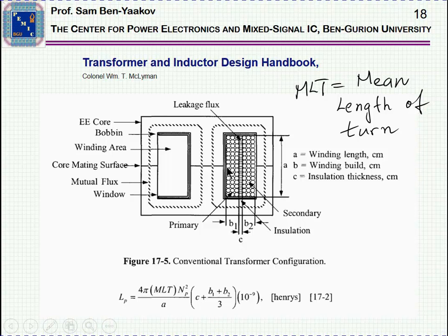In this case, you can do a bifilar winding. That is, you take the two windings and you wrap them together as if they were one wire. By this, you make the distances between them very small, and you improve the mutual inductance between them, and therefore the leakage would be much lower.